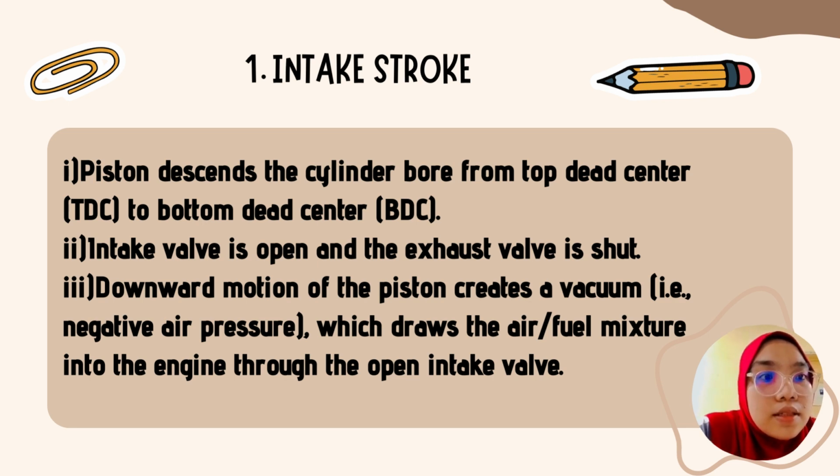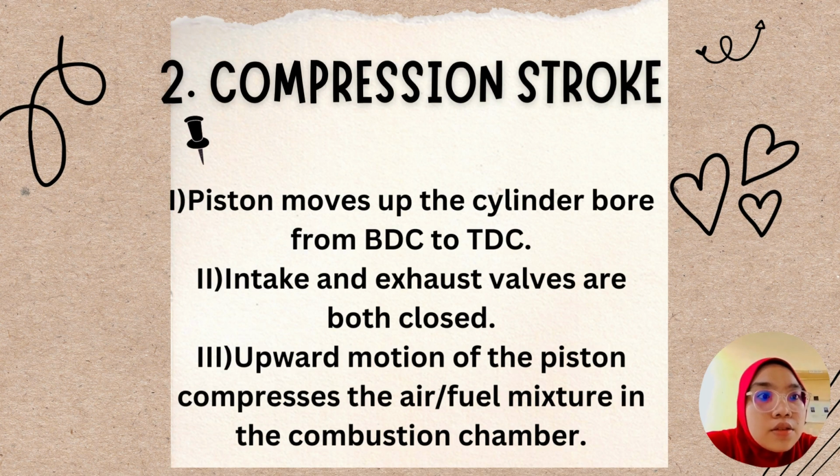So this is the intake stroke. First, the piston descends the cylinder from top dead center, TDC, to bottom dead center, BDC. Second, the intake valve is open and the exhaust valve is shut. Third, the downward motion of the piston creates a vacuum which draws the air or fuel mixture into the engine through the open intake valve.